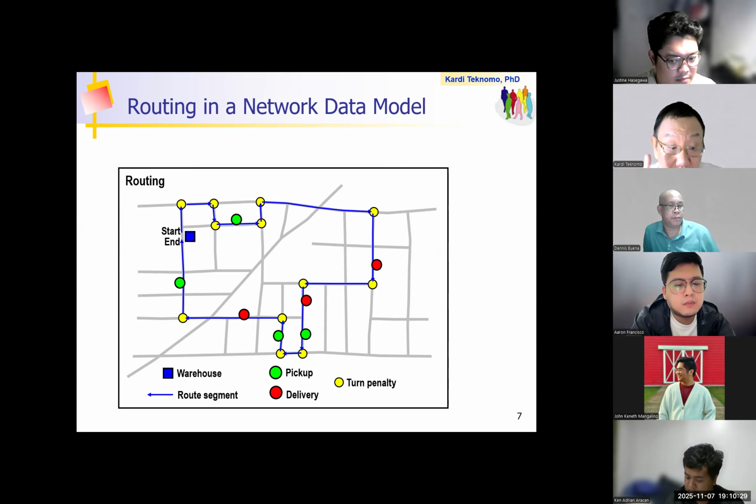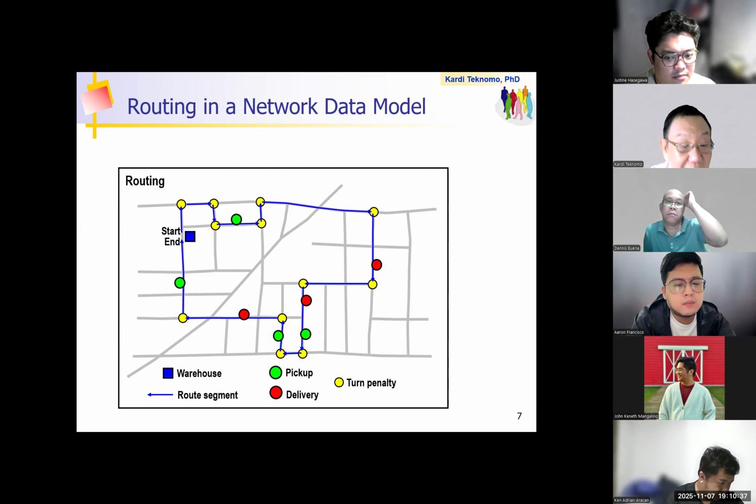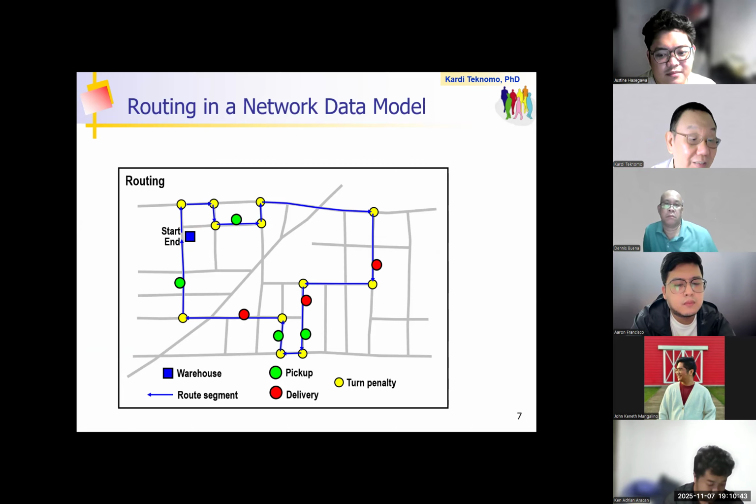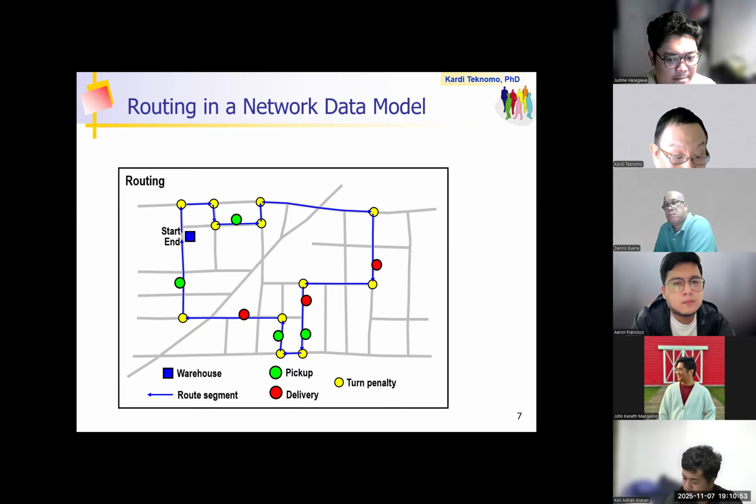Right? So this is the big assumption. Yeah, people do not always use the shortest route. Okay, but how are you going to assign? Okay, so the simplest is to use shortest distance first initially, right? And then on the next step, you will use the shortest route in terms of time. So instead of shortest distance, now you use shortest time.